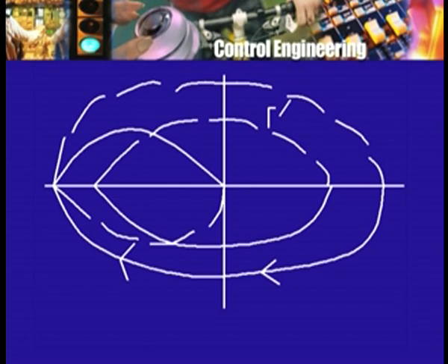And similarly, for the mirror image, the dashed curve will now be like this, and the remaining dashed curve will be like this. The S along the semicircle part still remains very close to the origin, because multiplication by 2 is not going to change it very much. So, now the image contour looks like this. Let me trace it. Starting at low frequencies, I go like this, high frequencies along the semicircle, then low frequencies along the lower part of the j omega axis, and back to here.